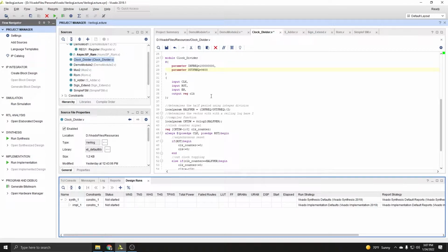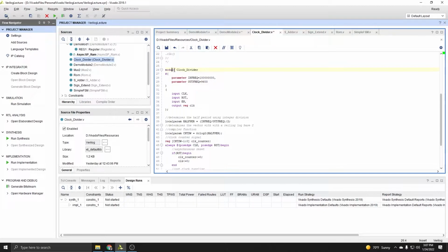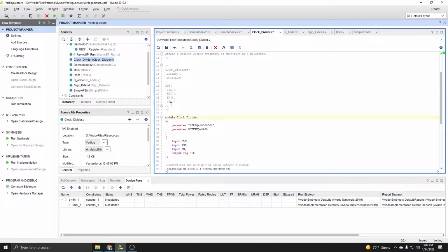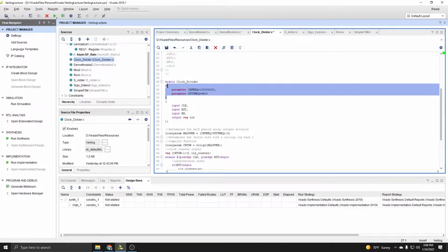But now let's actually get into creating modules. Now, as you can see, there's a general format for module creation. The first thing I'm going to be talking about, I'll talk about test benches later, are functional modules, and you create them with this format. The keyword module, then the name of your module, and then you have a section enclosed in parentheses that is prefixed by this pound sign here. Now this pound sign and then enclosed parentheses is the section for your parameters of the module.